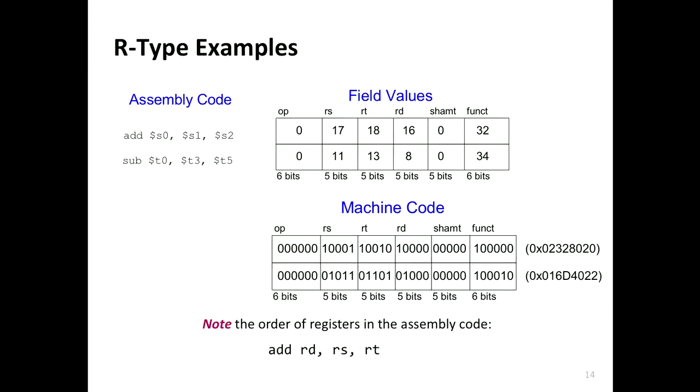You're going to read the values in S1 and S2, which means you are going to read the values of the source register, that is RS and RT. When you read out, you're going to read from the register file. So you're going to need RS and RT as the output. And when you write back the result, you're going to feed it into the register file. So you need it as the input. Understood?